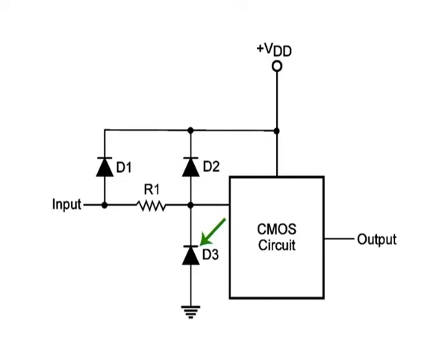the input terminals. Diode D1 does not contribute to input protection. It is a distributed PN junction present owing to the diffusion process used for fabrication of resistor R1. The protection diodes remain reverse biased for the normal input voltage range of 0 to VDD and therefore do not affect normal operation.